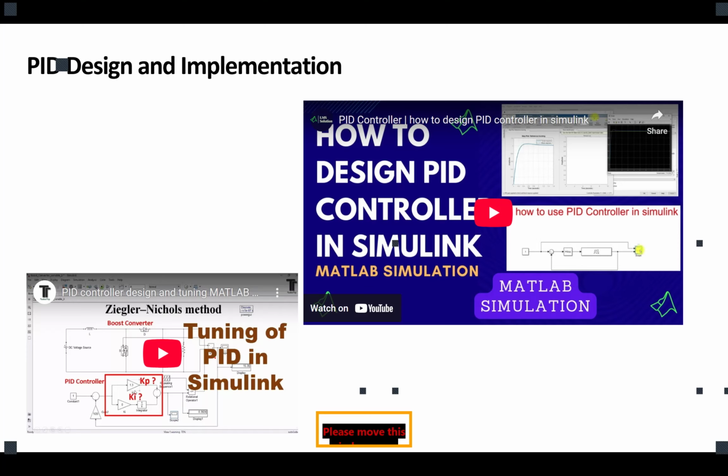It is better to have it, but if you want a cheaper, simpler control system in power systems, you could get rid of the derivative part because you already know how fast you are changing. Are we good? If you look at the video that I sent you as a hint before on Canvas for this assignment, it's a PI controller, not a PID controller. That's the reason. Good. Any question? No?